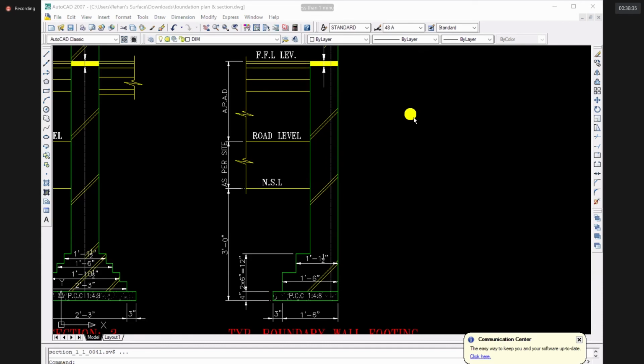4 5 feet below the road level, and then again the soil is weak. So let's say the geotechnical engineer suggests that you have to go 5 feet below the NSL level. In such cases, other measures can be taken in order to save the masonry, right? And you can provide a lesser deep foundation for a non-load bearing wall. Otherwise, provide the same. That is a better option.